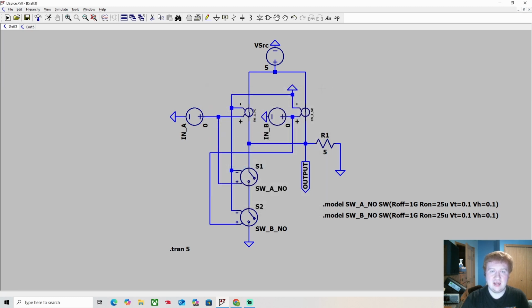So the NAND gate is the universal one that can turn into all the other gates if you set them up in the right way and right order. But anyway, the first thing that I want to cover is the idea of comparing MOSFETs to switches, because that's how these things are being set up in the first place. We're not going to use these transistors as any kind of amplifier. These are just being used as digital switches.